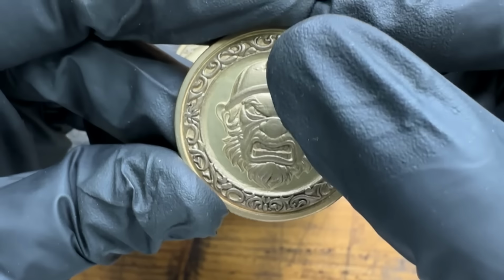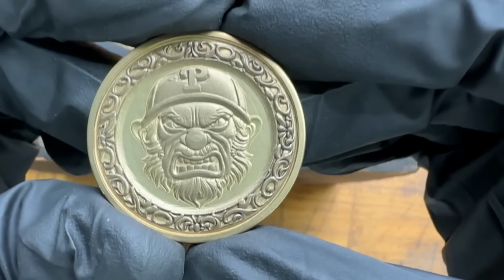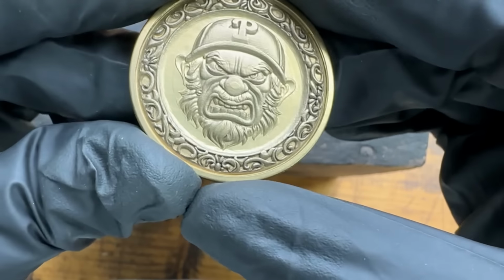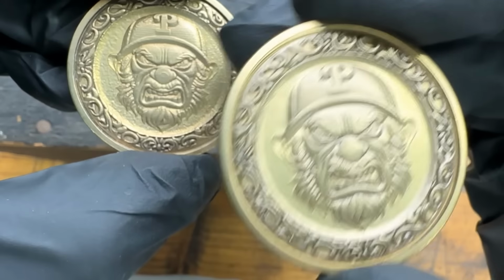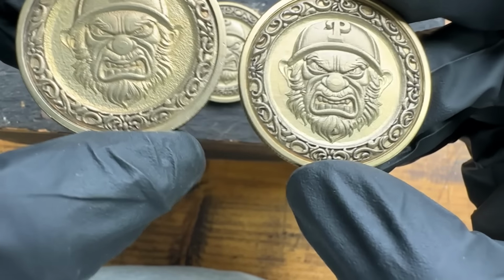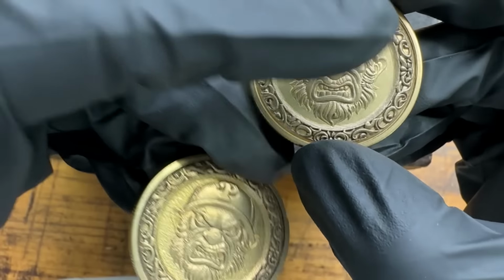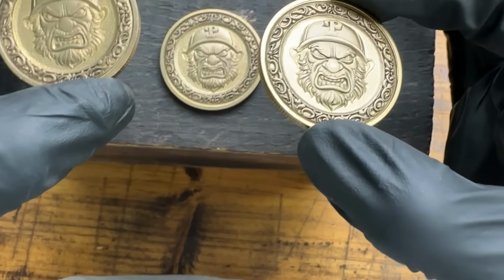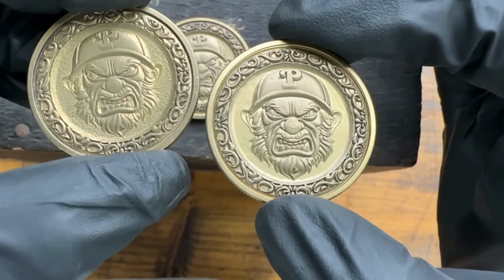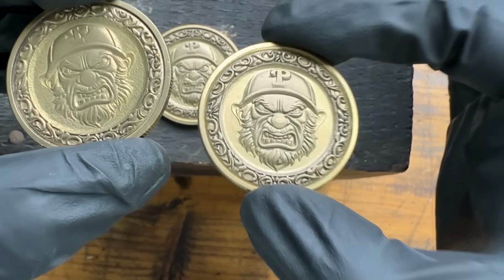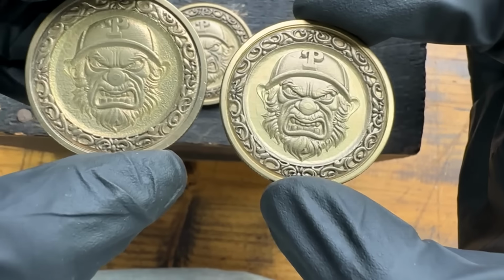I thought that since the frequency was so high and the power was pretty low, it wouldn't really engrave much, but there really isn't that much of a difference in depth going from the 48 kilohertz up to the 200 kilohertz, which kind of surprised me. I thought that I would get a lot more on this one versus this one, but it just goes to show that tweaking your frequency isn't going to bring gigantic changes to the depth that you're going for. You'd have to change your speed and your power to get more noticeable results.